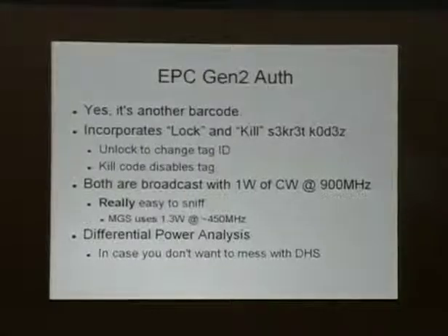In terms of authentication, yes, it's a barcode. It has a couple of secret codes. There's a lock code and a kill code. If you set the lock code, then you have to unlock the card in order to change the ID number on the card. That's all it does. The kill code makes the tag self-destruct. It makes it blow itself up and just cease operating. Once you've set these, you need to resend them again in order to take whatever action it is.